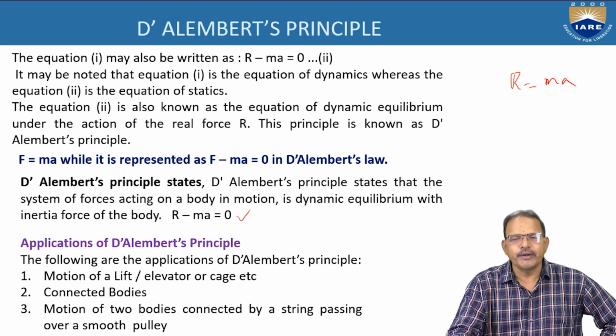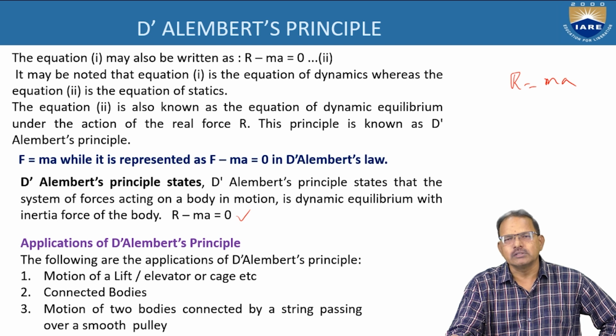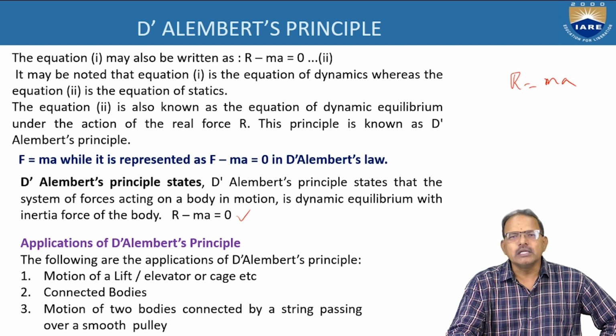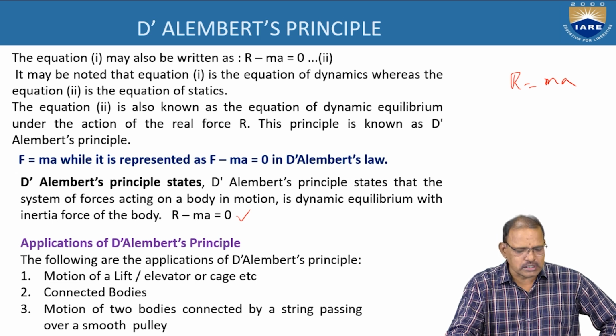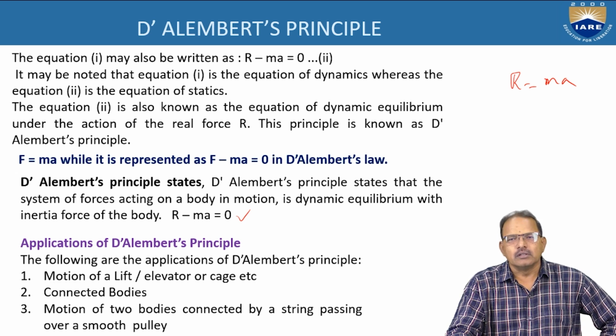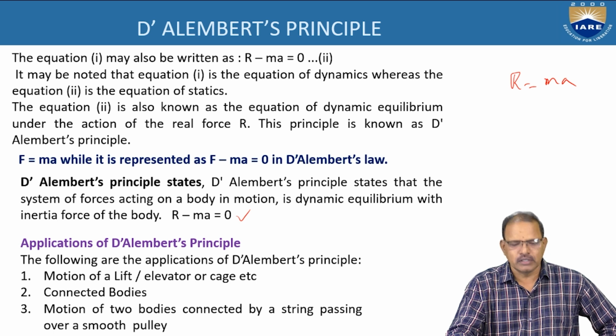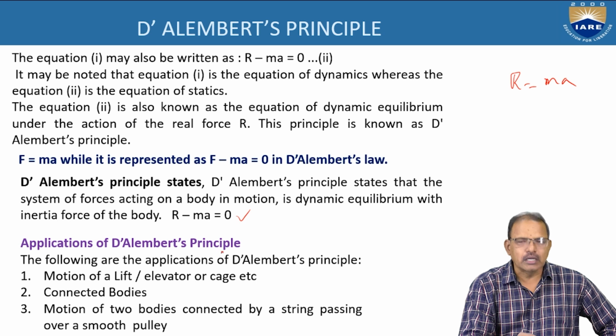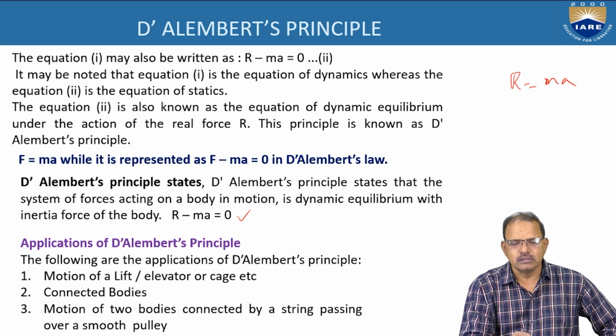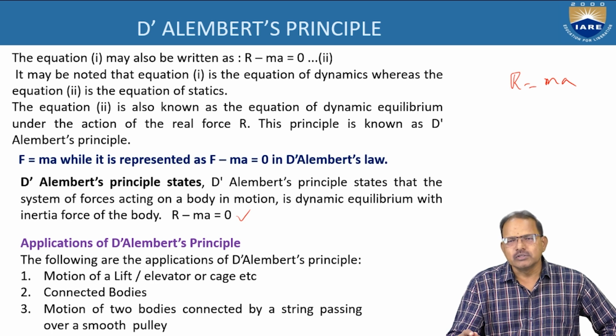This is the most important equation for analyzing forces in the engineering field, when both forces and acceleration are involved. The main applications of D'Alembert's principle are in the areas of lifts and connected bodies, such as the motion of two bodies connected by a string passing over a smooth pulley.